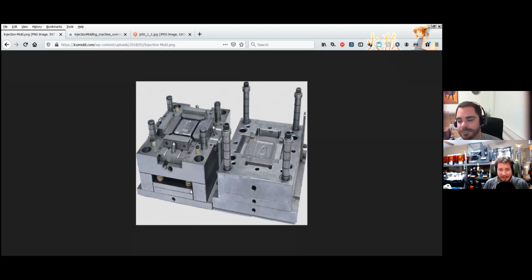It is the Lulzbot Taz 6. It uses a hexagon style hot end, which you can look up. It's not really widely used much anymore. And because of that, things like silicone heater socks don't exist. So you have to design and manufacture your own.